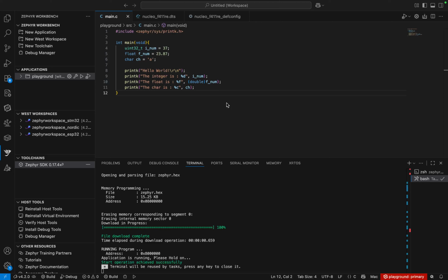You might want to turn on some LED to say, okay, yes, it is at this point turning on the LED, so then I can believe, because of where I wrote the code for this LED to be turned on, it is running this particular code, right? It is not like traditional programming on PCs, where because you already have a screen connected to your processor, it's easy to log things out and see them. However, we are able to achieve a similar thing in embedded systems.